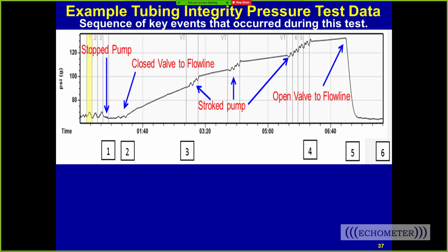On some of these horizontal wells we are drilling lately, there can be a lot of gas in solution even with a pump intake pressure of 500 psi. If your pump intake pressure is 500 psi and you have a lot of gas in your tubing, it can flow off if the gas comes out of solution and your tubing pressure is, say, 200 psi. That gas coming out of solution from 500 psi to 200 psi is going to cause your well to flow off.